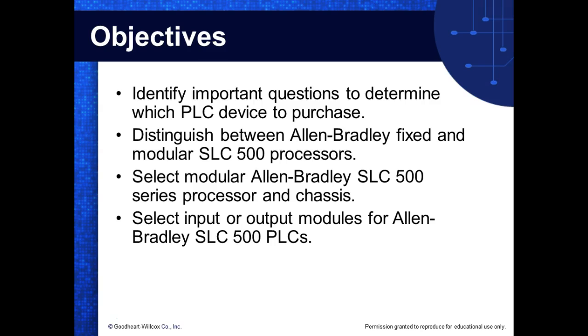I've tried to find out what processor Allen Bradley uses, but I haven't been able to. I haven't found that in documentation. I'm sure it's out there somewhere. Somebody could give it up. But we don't need to know that anyway because we're not going to program in the binary language of the computer. We're going to write it in a high-level language, and then we're going to compile it over into a machine language. So we're going to run an application on our computer that we call RSLogix 500. And it's going to allow us to do our programming. And then when we get ready to download it into the PLC, then it'll compile it over.